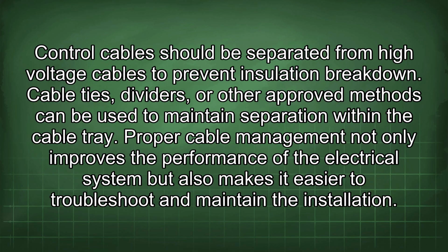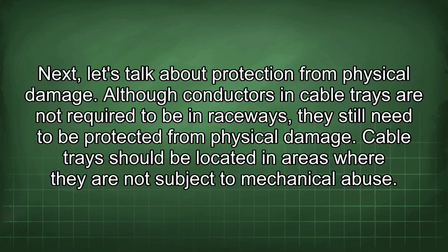Cable ties, dividers, or other approved methods can be used to maintain separation within the cable tray. Proper cable management not only improves the performance of the electrical system, but also makes it easier to troubleshoot and maintain the installation. Next, let's talk about protection from physical damage.